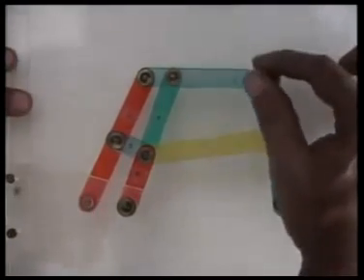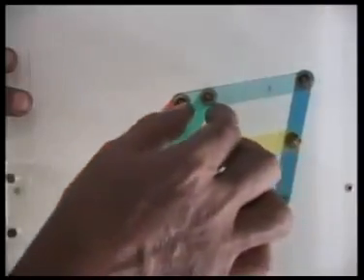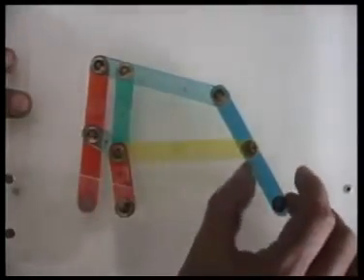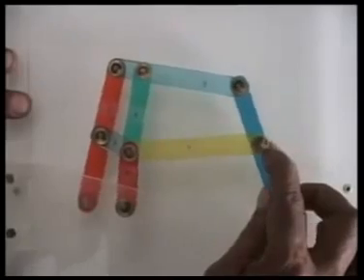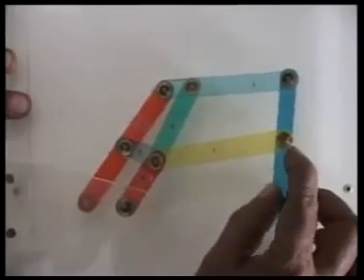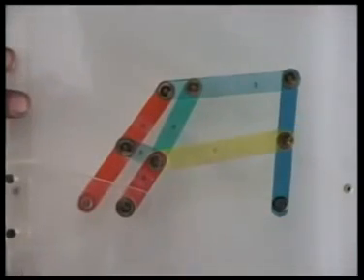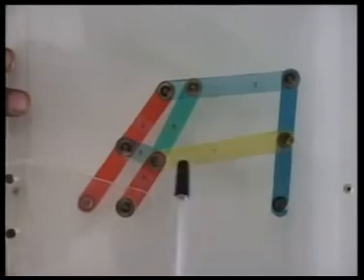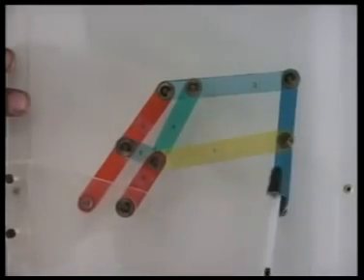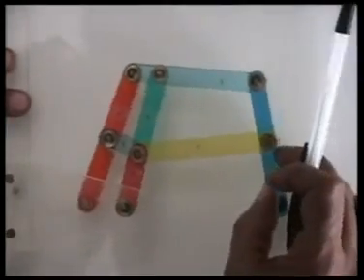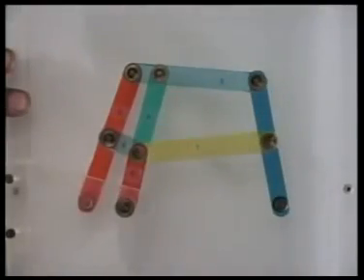But however, as we see, this mechanism can be moved very easily and there is a unique input-output relationship. That means the effective degree of freedom of this mechanism is 1. That is only because of the special dimensions. If we change any of these points a little bit, this will really become a structure and no relative movement would be possible.